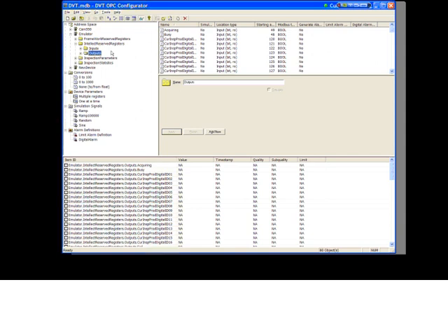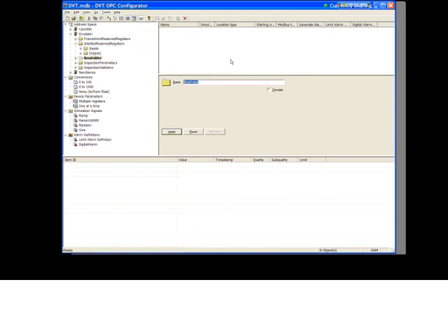And the way this is done is you right-click on your device, and under the new option in the context menu, you can create either a new folder or a new data item. Depending on how you want to organize your data, you may want to create a folder, and I don't know, call it custom data. Apply. I'm going to turn off monitoring view here.